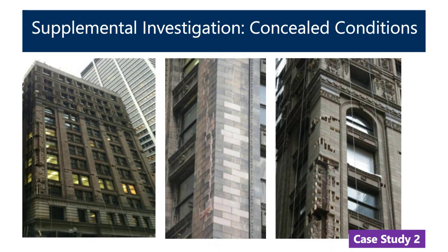One of the other aspects of supplemental investigation that is incredibly important is understanding its concealed conditions. What's going on behind the face of the masonry, and how is that related to the distress that we're seeing? And so here you sort of see the building taken apart, understanding how it's moving, and then also in the center image, showing that repairs had been done previously, but not necessarily understanding the cause of distress, and that those were needing to be repaired again.